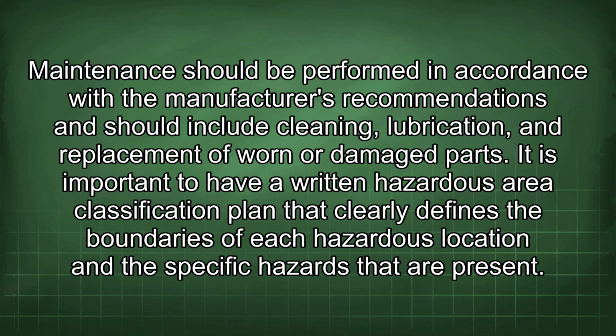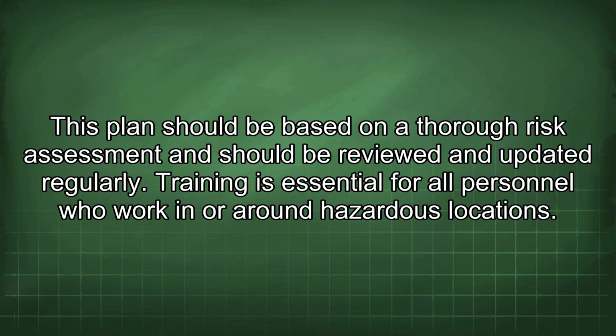It is important to have a written hazardous area classification plan that clearly defines the boundaries of each hazardous location and the specific hazards that are present. This plan should be based on a thorough risk assessment and should be reviewed and updated regularly.